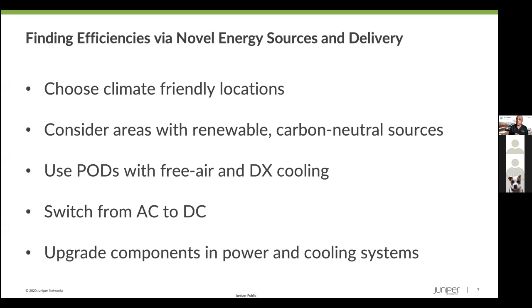People are building edge clouds. That means they're building data centers in central offices of the service providers or somewhere closer to the customers, which are enterprises mostly. And that means you continue to innovate in energy efficiency. So for example, when you build a data center, people want to use pods with free air cooling or direct expansion cooling. So you do not have to use very expensive chilled air cooling or water-based cooling, right?